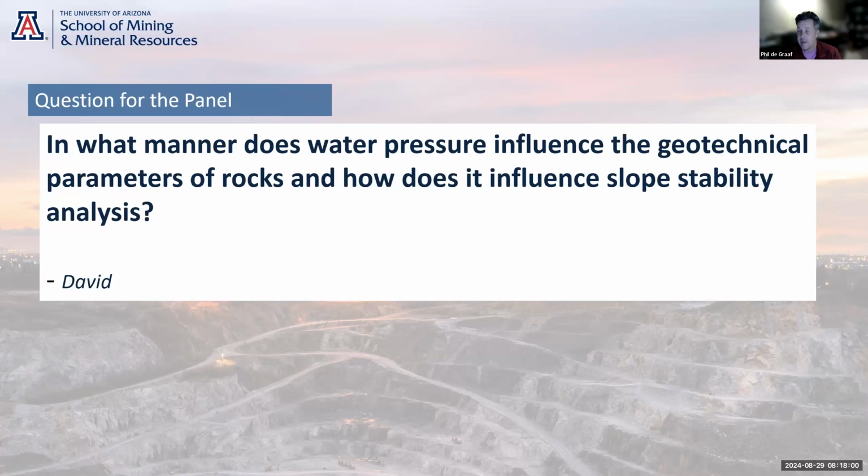And the other end member on that aspect would be long-term fluctuations, and there have been a couple of PhDs that have investigated this in more detail, demonstrating that there is actually a fair bit of ongoing rock mass damage with cyclical pore pressure loading and unloading, contributing to degrading of rock mass and joint strength as well. So the temporal aspect needs to be considered as well in this process. Yeah, totally agree.